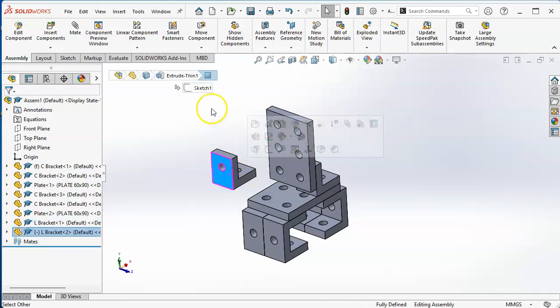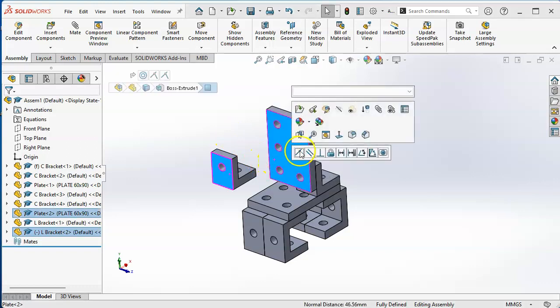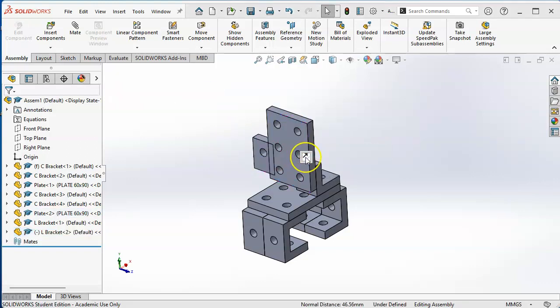And let's do a mate alignment here. Since we've been doing rotates, I got all my context things popping up. I'm going to do a select, control select, and I'm going to make that coincident. And then the flip mate alignment box allows me to change it. It does it kind of weird, but it's okay. And I could do that even if I set it to concentric.